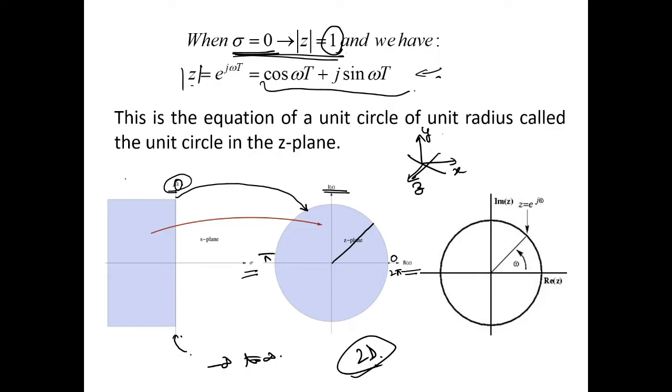So what would happen to the rest of the frequency components? As you go on increasing the frequency components, they will be overlapping on the same points. So this is called many to one mapping. Many frequencies are getting mapped into a single frequency. That is why band limiting is important. You need to do the band limiting so that this many to one mapping can be stopped.